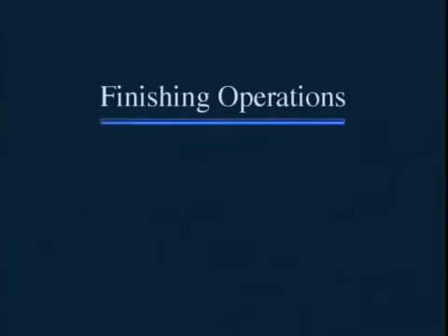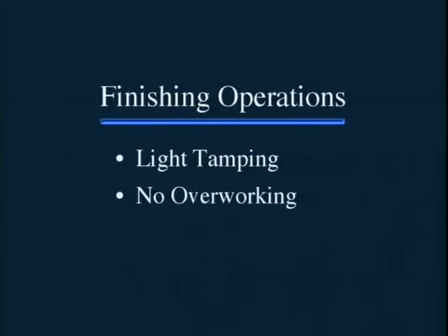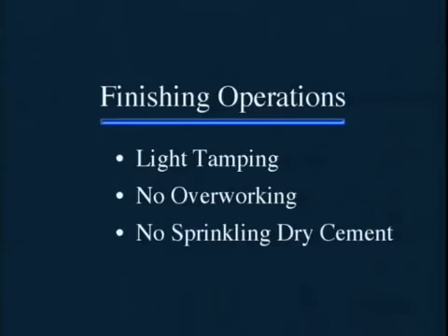The recommendations to prevent crazing cracks are rather straightforward. It's all in the finishing operations. Light tamping, no overworking, and don't sprinkle dry cement on the surface.